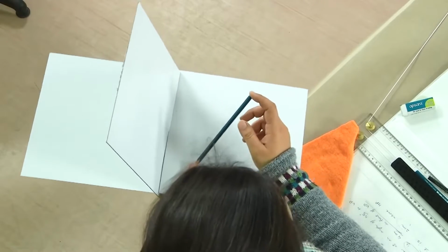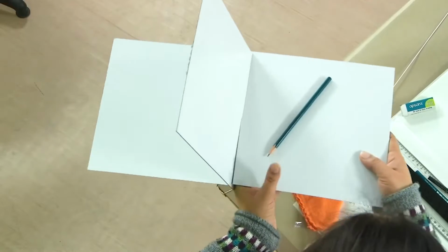If you essentially see, if it is inclined to one plane and we want to incline it to the other plane, we are moving it in a cone-like manner. So, let us understand this with the help of a cone. The movement is actually like that of a cone. Suppose there was a line which was making an angle of say 45 degrees and now it has to make an angle of 45 degrees with VP as well. We will raise it in such a manner that it moves like a cone.